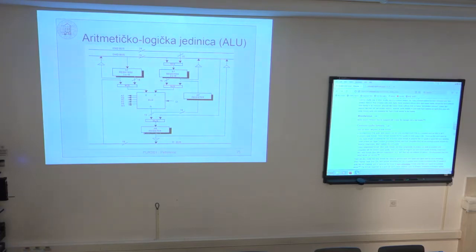And this feedback register is the same as result register of ALU, but exactly if I want to combine several assembly instructions where the previous instruction computes the argument for the next one, then I can store the intermediate result here in feedback register and use this intermediate result as a right side argument of our instruction instead of AY0, AY1.